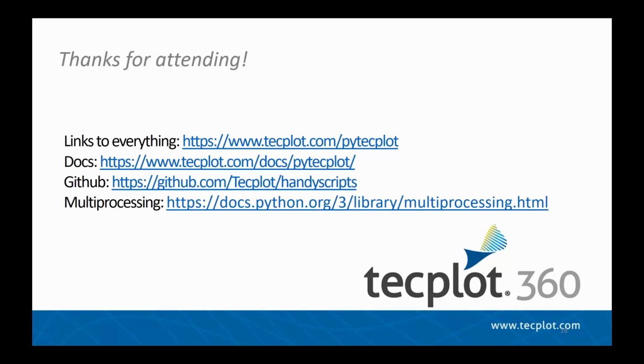Is session.stop required to clean up the temporary files? Can't you just let the process exit? Yes and no. One of the things that we noticed on Linux is we get a crash or a core dump on exit. The multiprocessing toolkit just terminates the process, and you'll get a core dump on Linux. So it really is important to call stop to make sure that Tecplot closes before the multiprocessing library terminates the process.